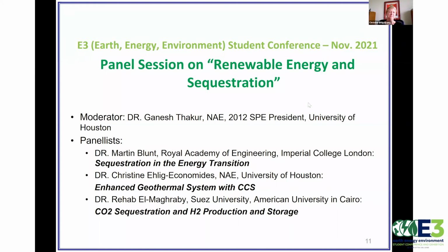Great. Any other questions from the audience? I would like to comment further on that. Okay. We're looking very closely at a tight integration for the blue hydrogen production where you collect the CO2 as you do for blue hydrogen and re-inject it into your methane or natural gas reservoir. So this is reservoir management of a new style for petroleum engineers. And it looks very, very interesting because in effect, this is enhanced gas recovery. Instead of EOR, we get to EGR. So you're asking, okay, that's methane. How do we get that to hydrogen? Well, the answer is what you heard. The produced methane is used to generate the hydrogen. So if you follow me, produce the methane, generate the hydrogen, collect the CO2, put that back into the reservoir, and thereby you're actually enhancing hydrogen through CO2, in my view.